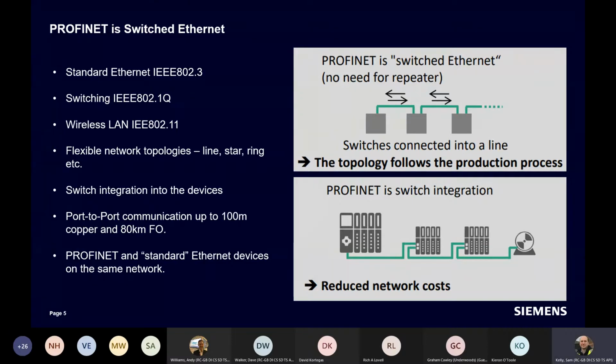From the Siemens portfolio, you may use a media converter to convert from the copper to the fiber, or if you are familiar with the Siemens portfolio, you may use, for example, the ET200SP remote I/O with a fiber optic bus adapter, to go straight to fiber on there. And if you are using fiber optic, with some technologies we can go distances of up to 80 kilometers. So you can see here it's very flexible in the types of distances that we can serve.